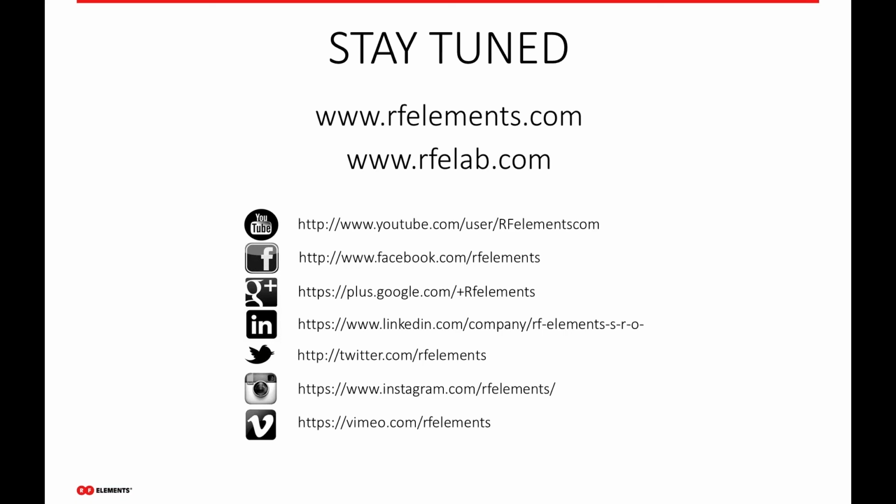And it's not about gain, it's about the coverage that you want. Some of the more successful WISPs are actually using wider horns versus the narrower ones, right? So if you look at our spec sheets, they show you the -3 to -6 beam width. And what other people are doing is using kind of a 40-degree horn based on a -3 beam width of 30 degrees and giving some overlap.